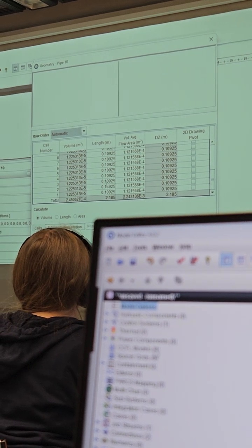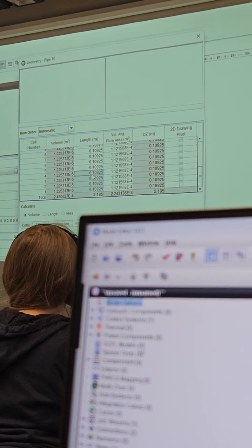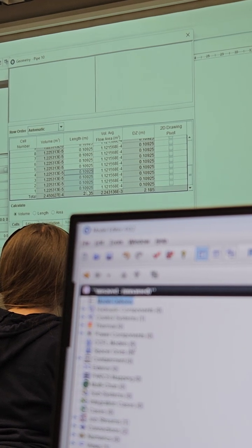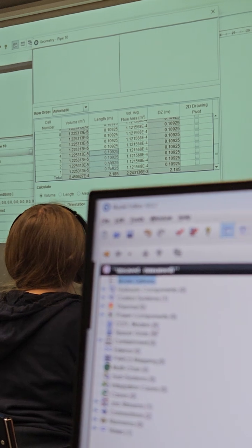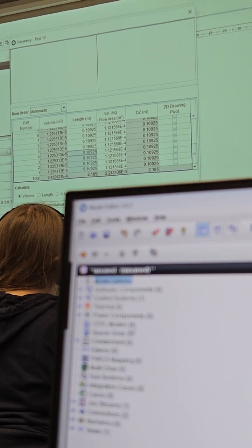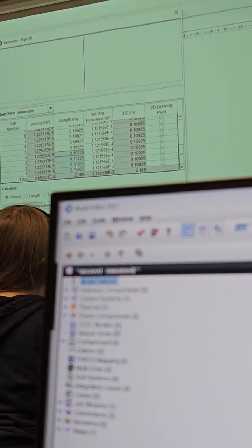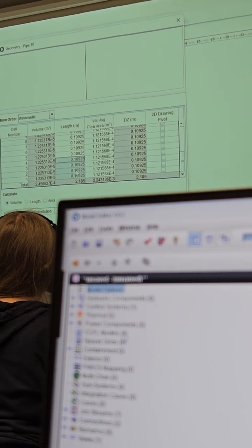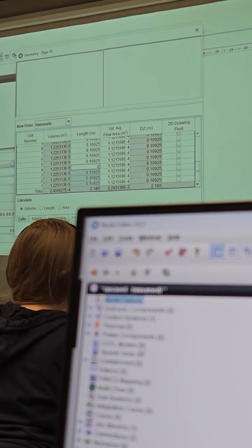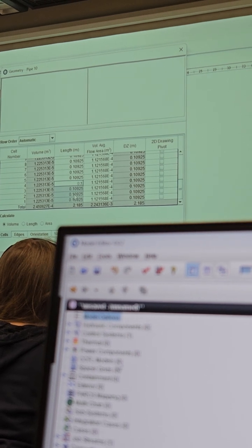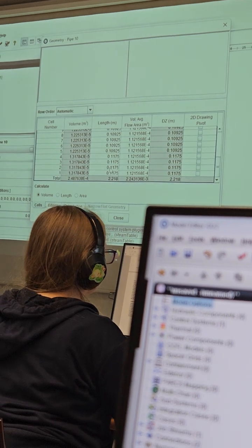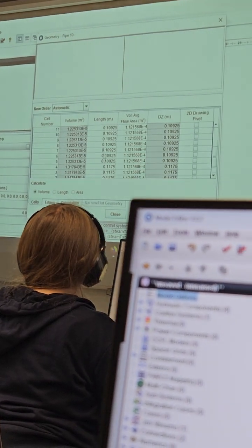So I have my own pre-calculation, but you could do your own. You can divide into a different number of cells, not exactly 20, 40, 100. It depends on the accuracy needed in your calculation. For this case, 20 is quite enough from my point of view. So then, for example, for the first 4 cells, I defined the length as 0.1175. So these 4 cells are exactly 470 millimeters.